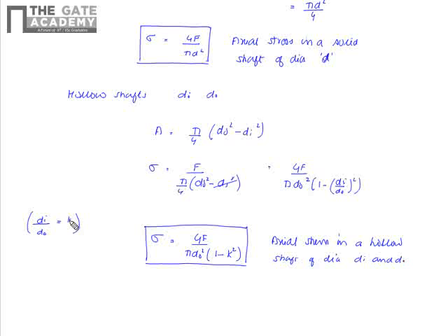And in this axial stress, if the axial force is compressive, we know that when a compressive axial force is acting, there is a possibility of buckling. So we have to take some column action factor. Then we take alpha as the column action factor.